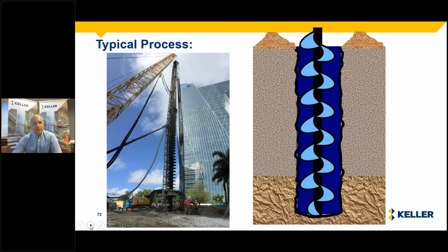At that stage, grout will be poured at the bottom, called the head of pressure, and this head of pressure is designed so that when we begin to remove the auger, the pressure of the soil trying to push inside and make it collapse will be supported by the head of pressure of the grout, which is heavier in density than typical soils. That means a calculation has to be made to see how much head of grout is being pumped at the bottom.